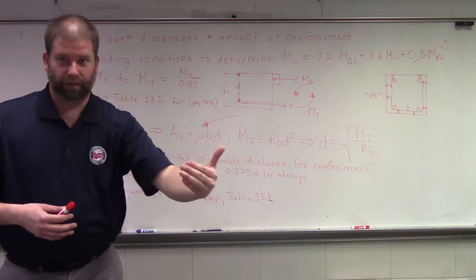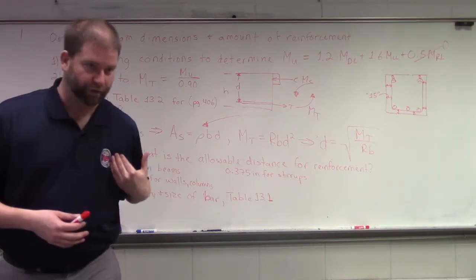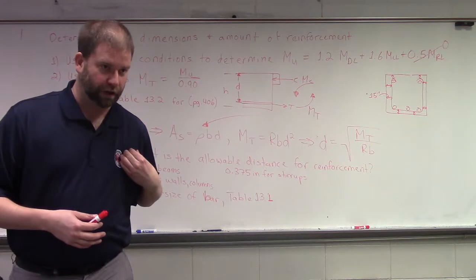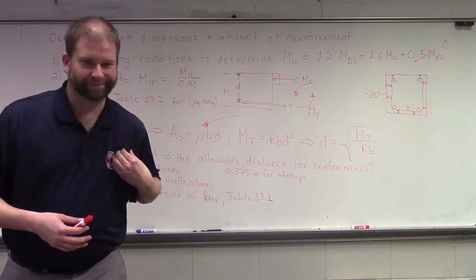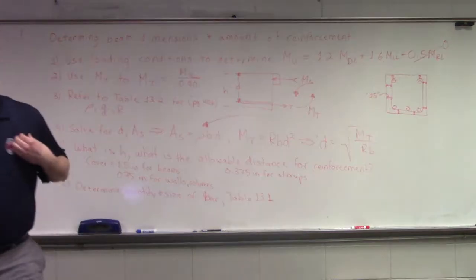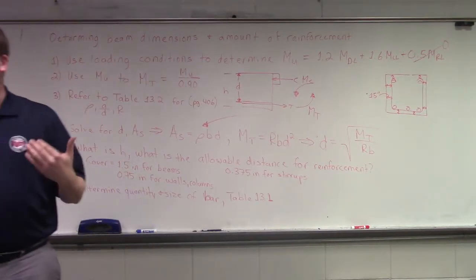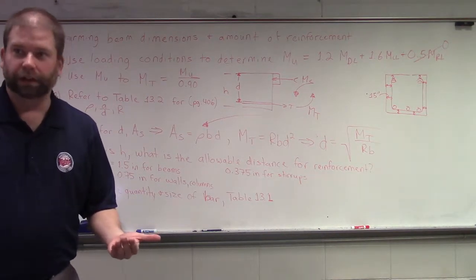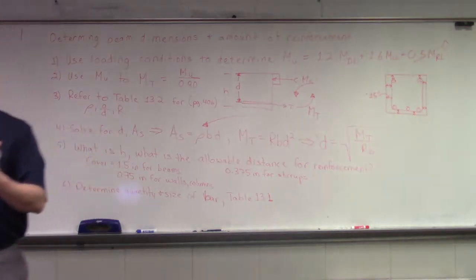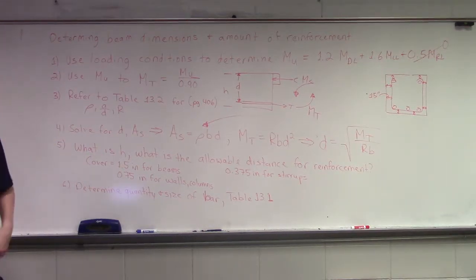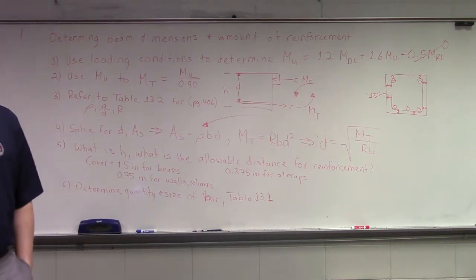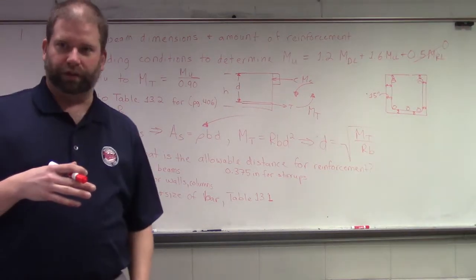And the ready mix producer says, okay, now I have to determine how to make this concrete. If you go to the ready mix producer and say, Mr. Ready Mix Producer, you've got 3/4 inch openings, he is not going to be able to come back and say, you know what? 3/4 inch aggregate is the only way I'm rolling. They've got to figure out how to make it with 3/8 inch aggregate.